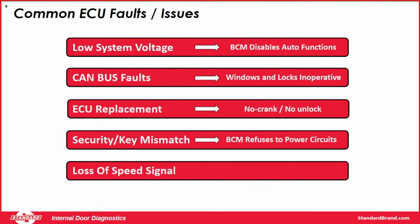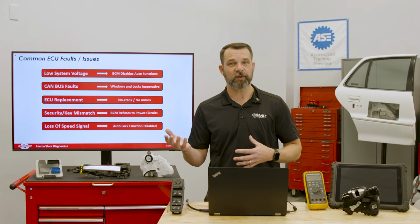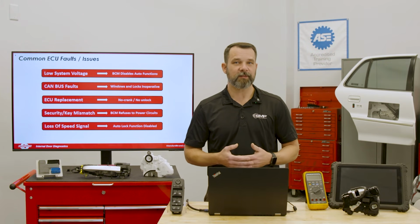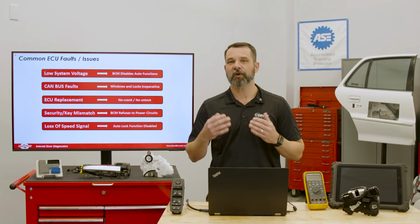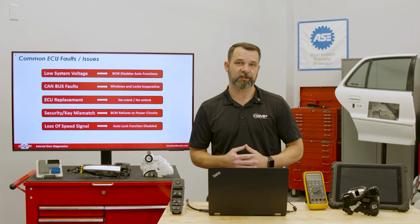And if there's a security key mismatch, the BCM is just going to refuse to power the lock or unlock circuits. And then, of course, if we have a loss of speed signal, the auto lock function will also be disabled. And so, oftentimes customers come in thinking they have a bad window motor or a bad window switch, but the real problem is actually upstream. Maybe it's a low system voltage, maybe it's a CAN network fault or a mismatch between the ECU and the BCM. In these modern vehicles, communication issues are going to be a huge deal when it comes to body features and whether they work or completely shut down.